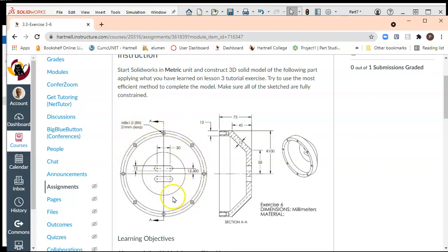holes, of which there are 8, as you see, 8x. And M8 is the size. That's the metric designation, where the nominal size is 8, and 1 is the thread pitch, I believe, for the threaded hole. So you have that designation for metric, and 21 mm deep. That means it doesn't go all the way through. This hole doesn't go all the way through.